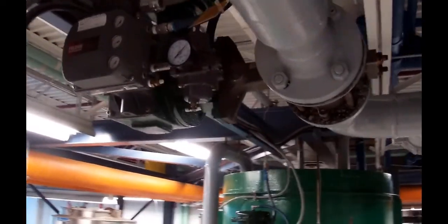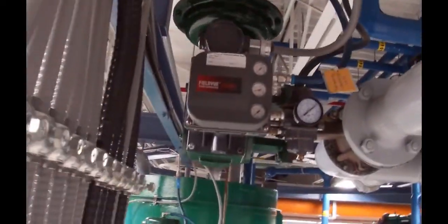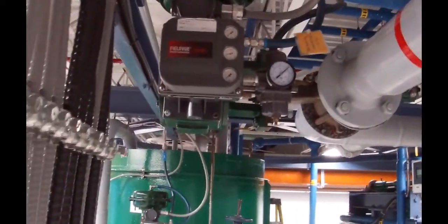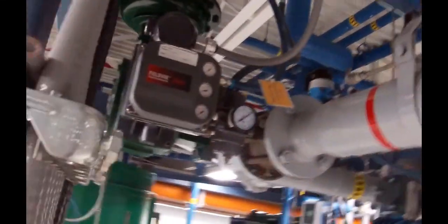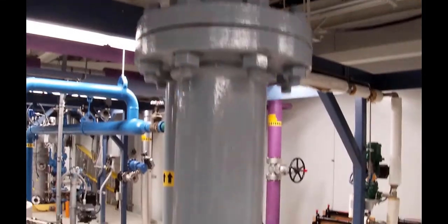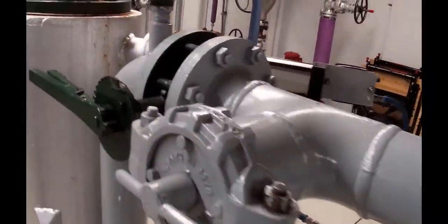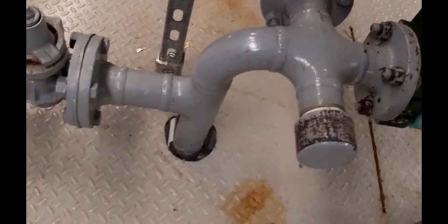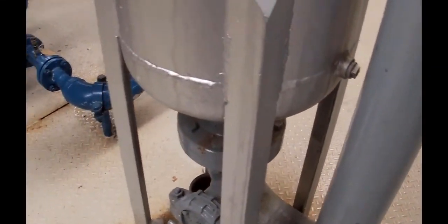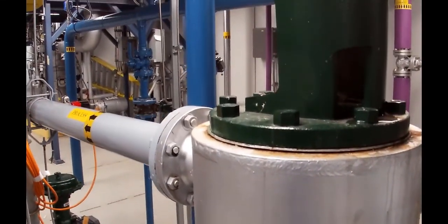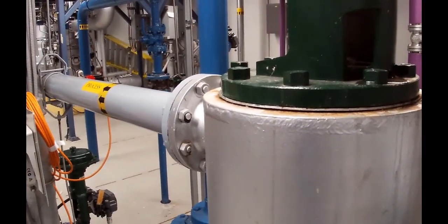Go around that a little bit. So there's the control valve with a DVC 6200 positioner on it. From there it comes along through here, down to there, and the 3.5% stock now comes and meets at 1.75 coming up from here. They go up to a mixer before they go to the total flow line.